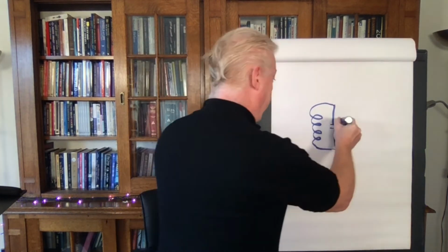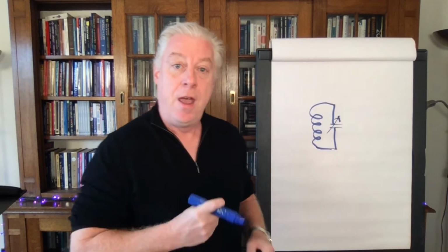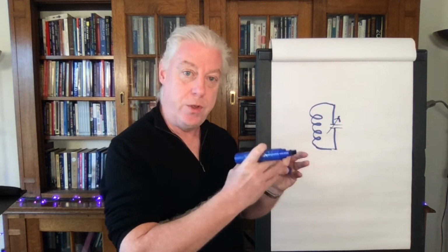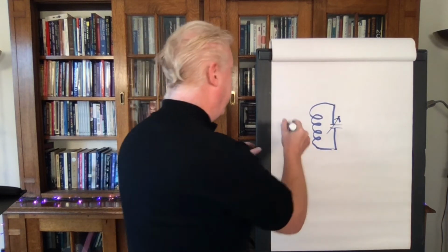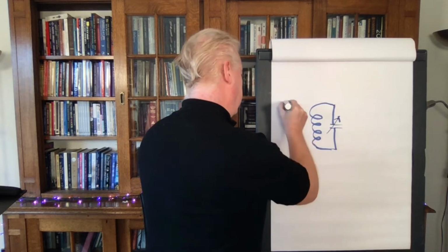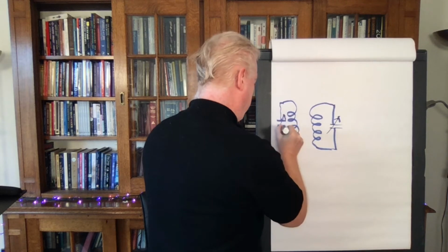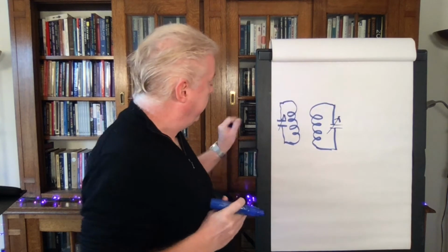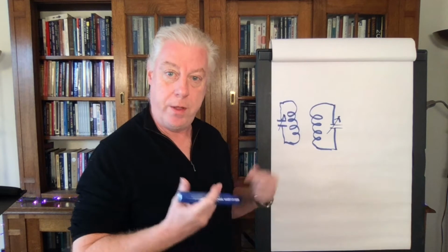If we make this what's called a variable capacitor or a variable condenser, then we can actually change the resonant frequency that tuned circuit resonates at. So if we got a tuned circuit here, and we could set them to the same frequency, then we'd get a resonance between the two things. And this is what we've got with radio.